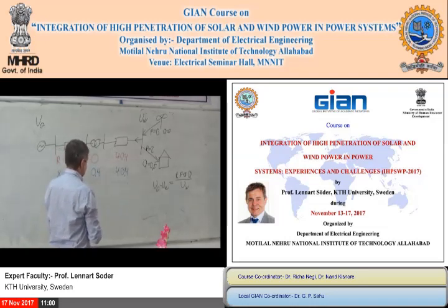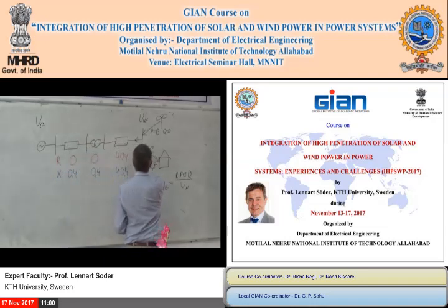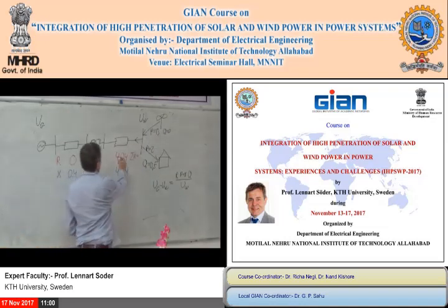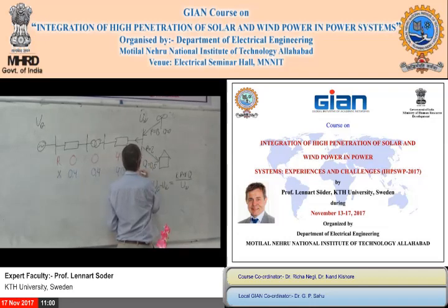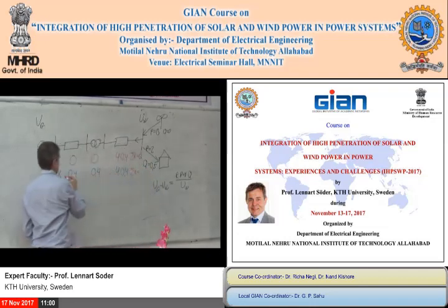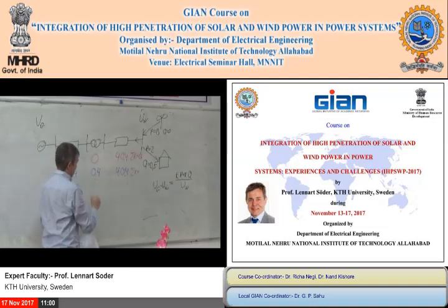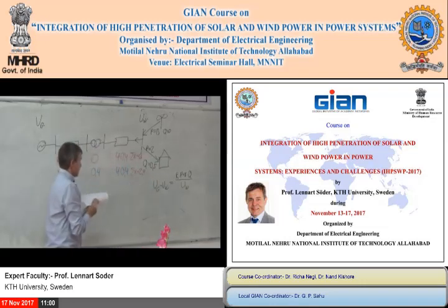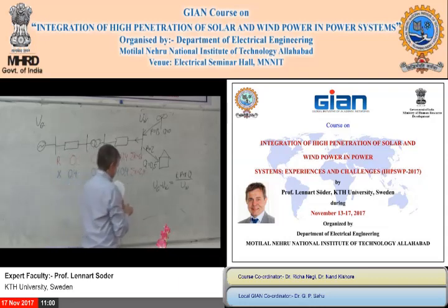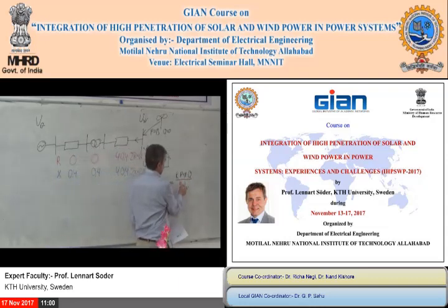And then what you can see is that the total sum of R here, in this point, is equal to 4 times 0.4, so it's 1.6. Sum of X is equal to 6 times 0.4, so it's 2.4. So this means that the X is larger than the R. And if the X is larger than the R, this means that Q has more impact than P.